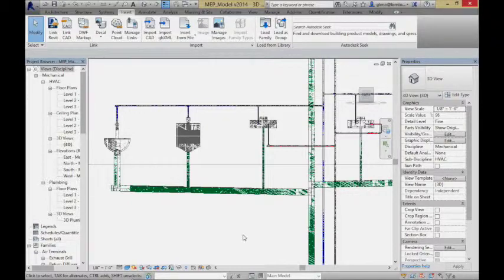What will often happen is it may be smaller at the end because it's only servicing a single load, but as you add more loads to it, as you head towards the riser, it will keep getting thicker and thicker as you need to allow additional capacity for things that could come from each of those different fixtures. So we tend to have pipes that come on down.